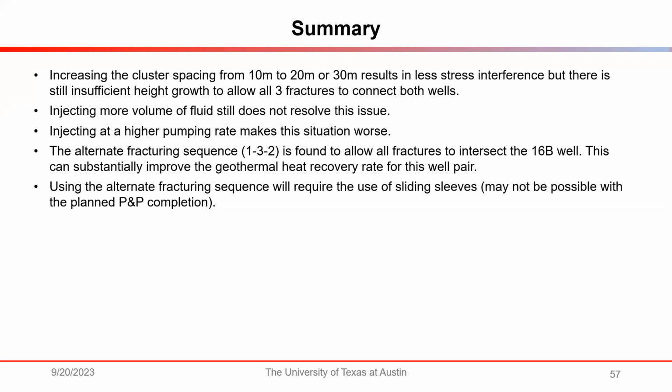Which is again just a very different shape to natural fractures than the models we've been using. Would you suggest that we try to vary the height as well? Well, I would suggest that you have the height the same as the length. So we always used an aspect ratio of 1 on our fractures, because these are igneous intrusive rocks where you're not expecting the heights to be limited by, say, like in sedimentary rock, different lithologic boundaries. Although we do have some lithologic boundaries, but we don't expect them to be necessarily horizontal features.